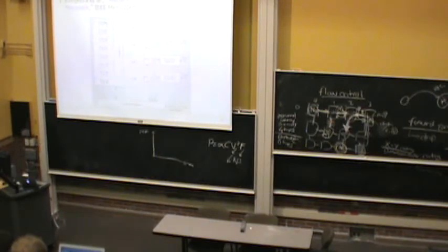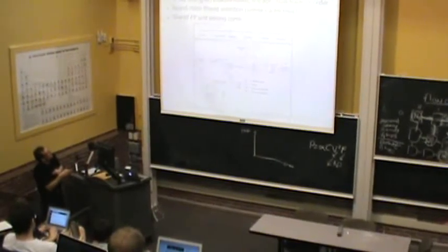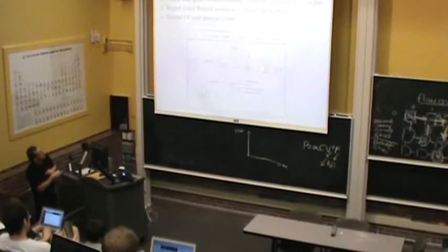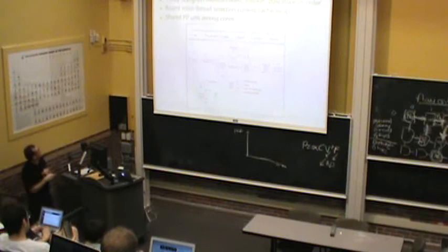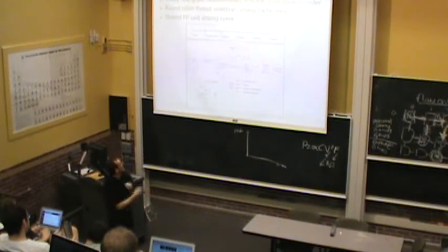So if you look at this, you have 8 Spark cores, simple cores, and this is the system architecture. But let's take a look at the core itself. It's simple. It has a 6-stage pipeline. It is dual issue. It's in order. There is no out-of-order scheduling. And it has fine-grained multi-threading. There's no branch prediction. There is no interlocking. And it's essentially a fine-grained multi-threaded machine.